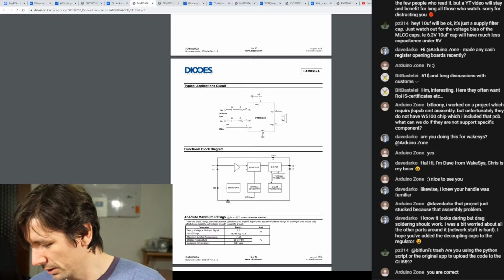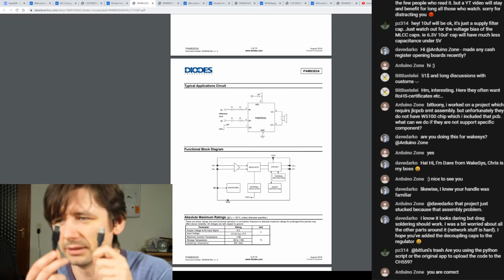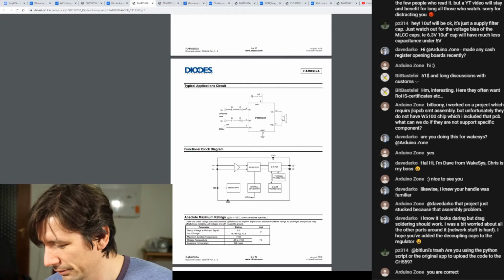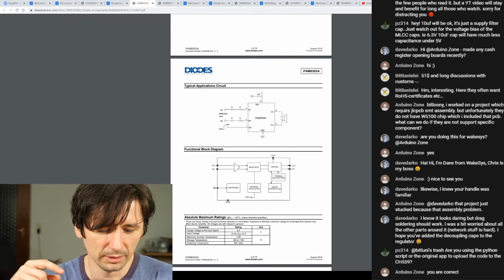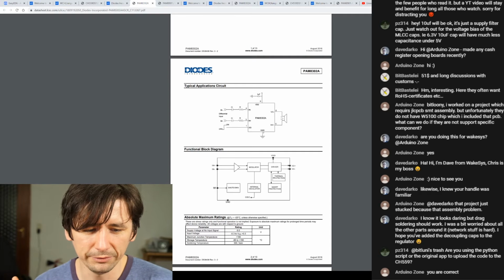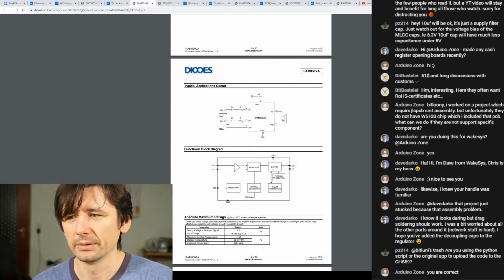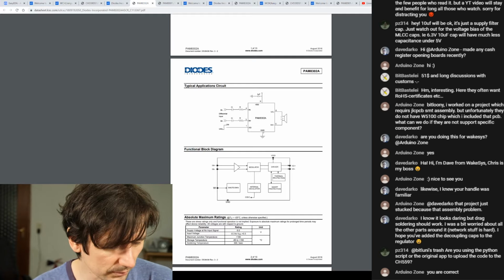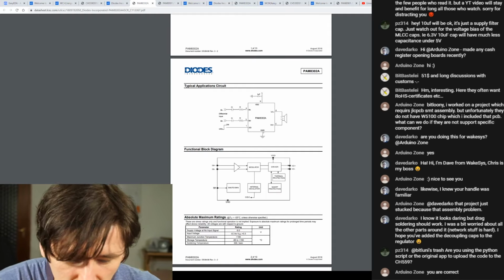you have to use the special cable with the male USB-A on both sides. So if you don't have that, you won't be able to update the firmware on the CH559. So in the sense of scaling up, it has to be a simple update procedure for the driver chip. That's why I thought, okay, I have to be able to update the CH559 over the UART from the ESP32, and that's what I will do in the end.